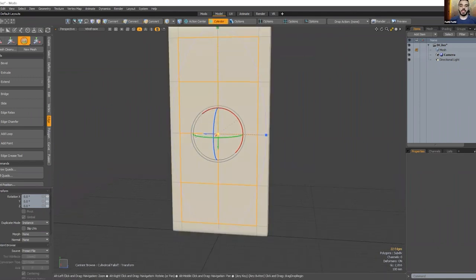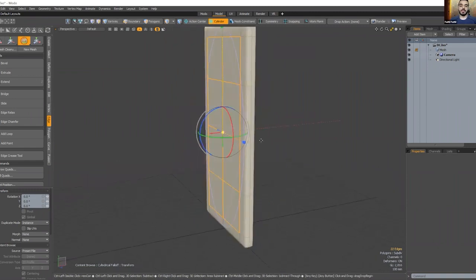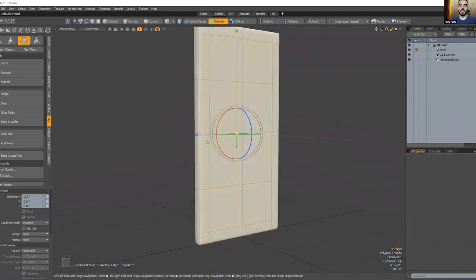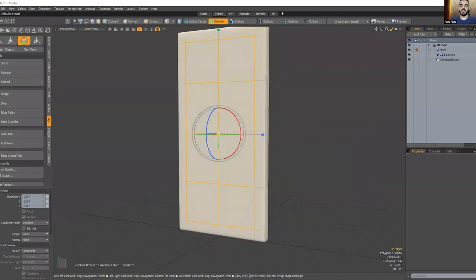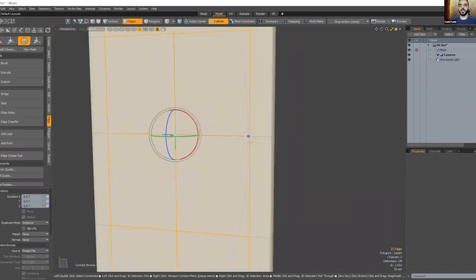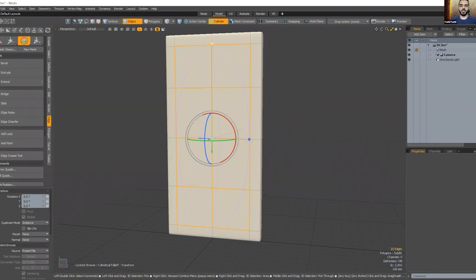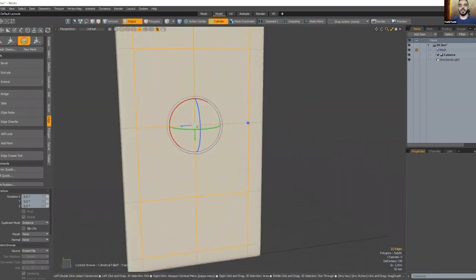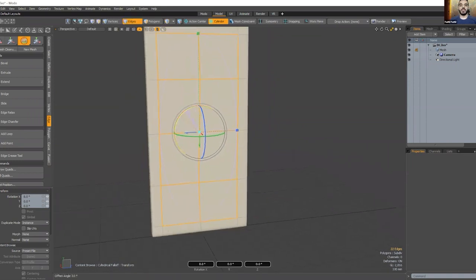And what this is giving me is a cylinder here, as you can see. It's purple, and you can see that this is already distributing the force vertically. So what I'm going to do is move this inward so that it doesn't move these edges. So there's going to be no force at this point. I'm just going to move this downward. So now you actually have the forces being applied in the center. So when you move this, the force is only going to happen at the center.